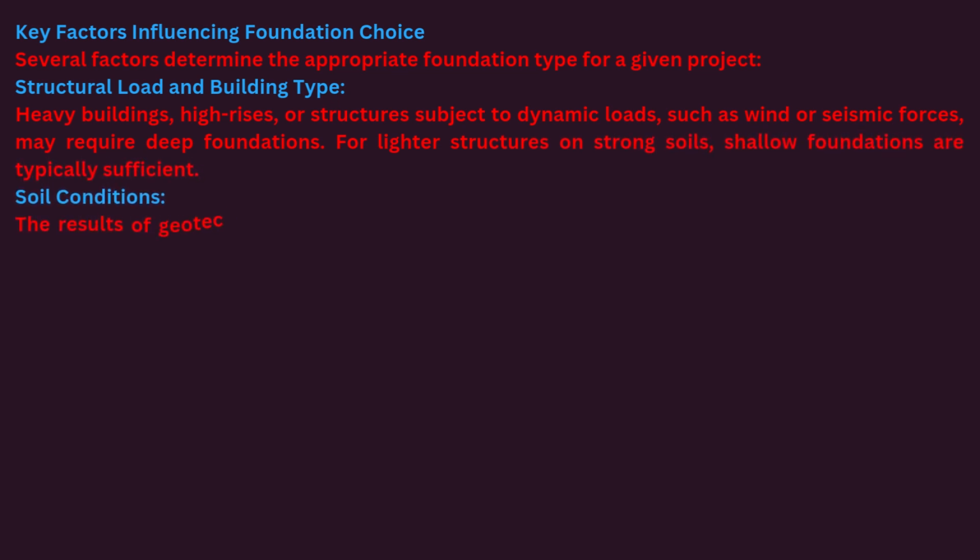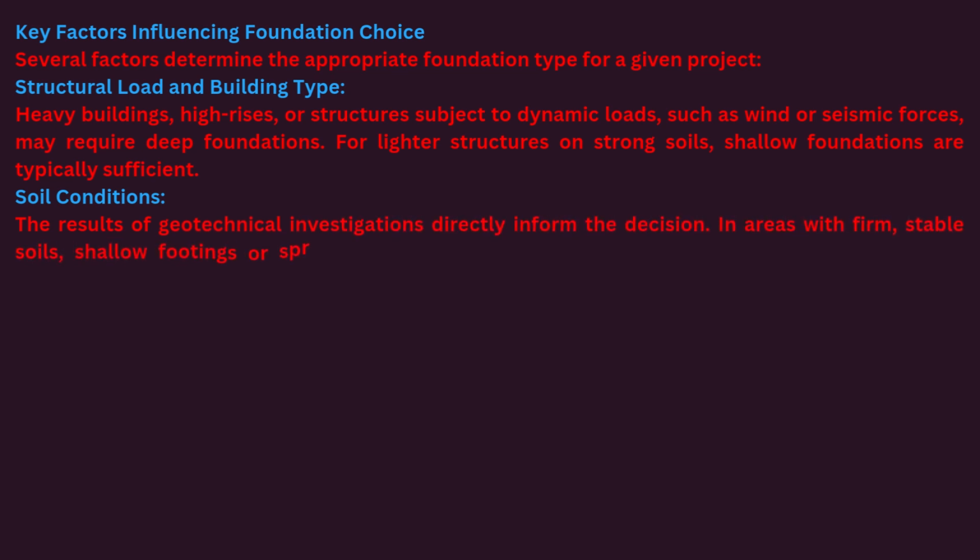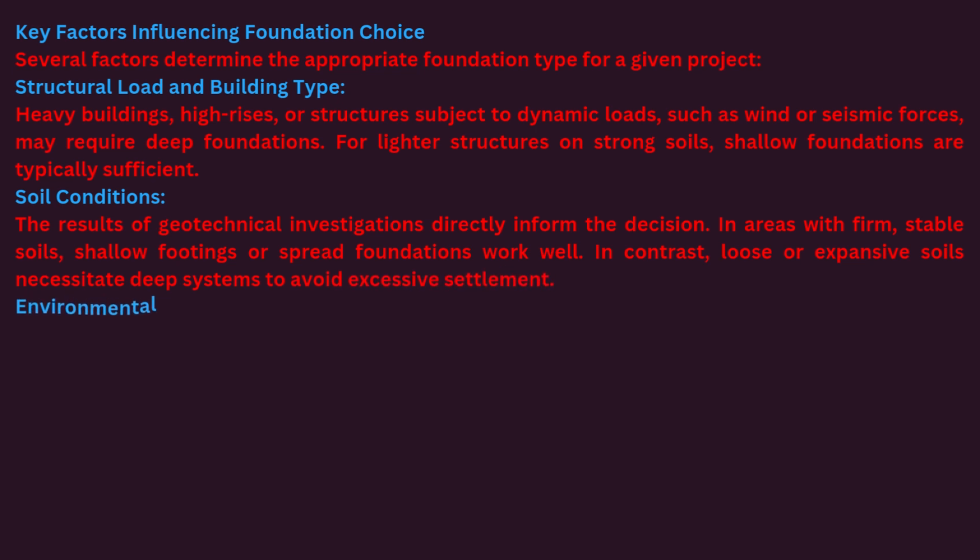Soil conditions. The results of geotechnical investigations directly inform the decision. In areas with firm, stable soils, shallow footings or spread foundations work well. In contrast, loose or expansive soils necessitate deep systems to avoid excessive settlement.